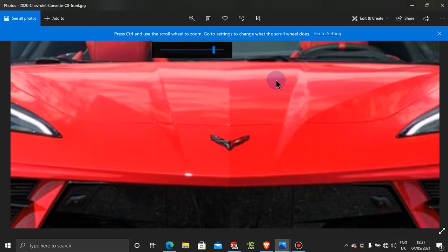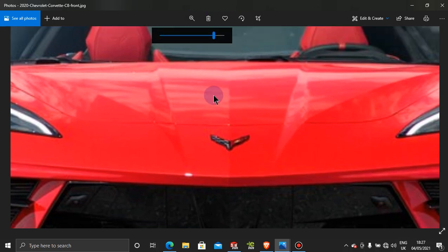there's probably a little bit of curvature, but we managed to create the V shape that we were looking for. I think the V shape that we introduced in our surface is a bit too sharp, so we might shallow it out a bit, or we see how it works out once we create these sections here, and then if it works out, we're going to leave it. If not, then we're going to make the curvature a bit shallower.